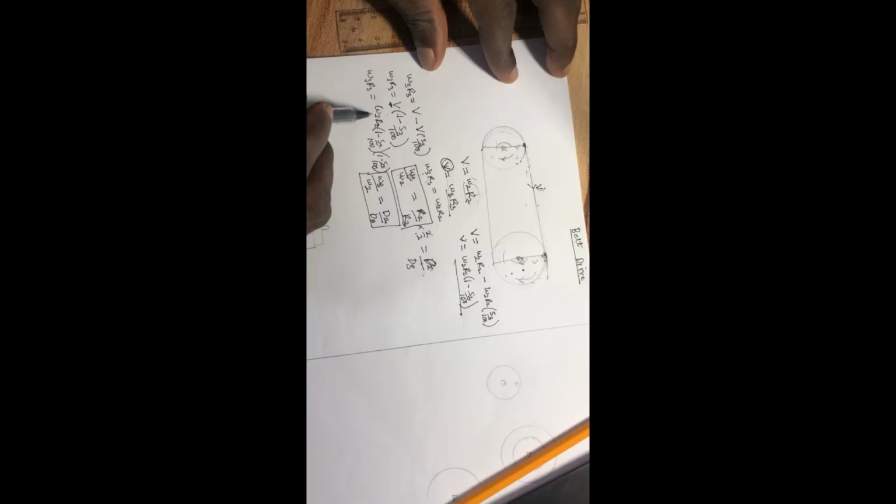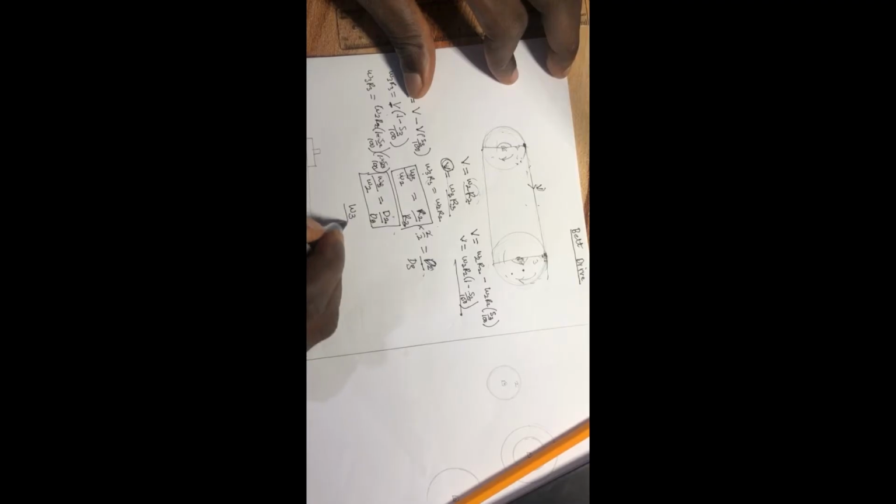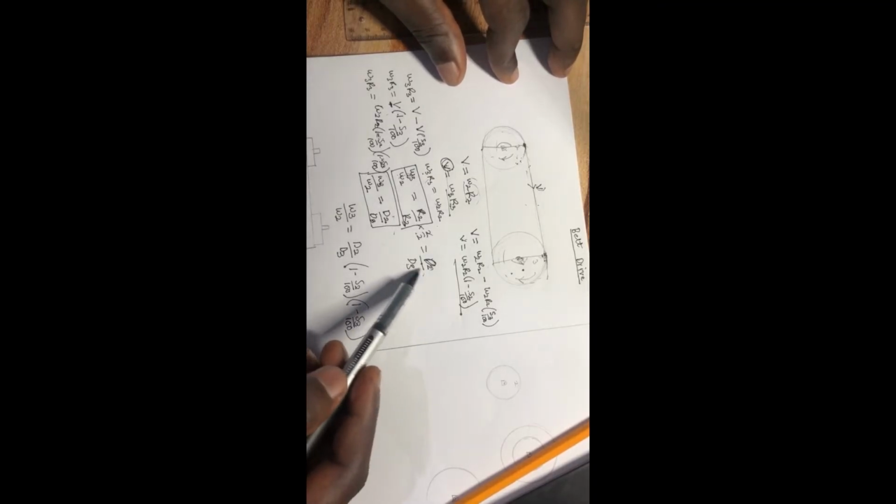That means when we are accounting for slip, you see we have this omega 3 R3, omega 2 R2, which is similar to what we had here. So we can deal with that. The only thing here is that we have the slip. So omega 3 on omega 2 will be equal to D2 on D3 multiplying 1 minus S2 on 100 multiplying 1 minus S3 on 100. Understand that? So the difference here is that we are multiplying 1 minus the slip of the driver pulley and then multiplying 1 minus the slip of the driven pulley.